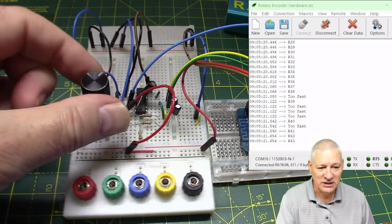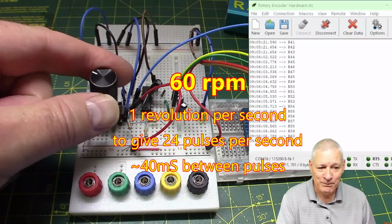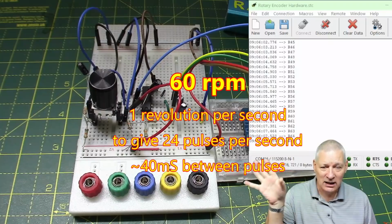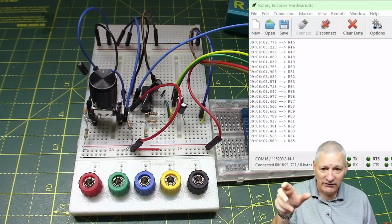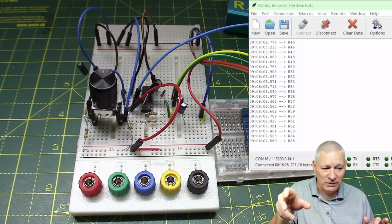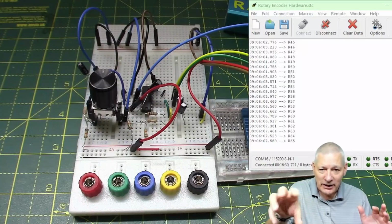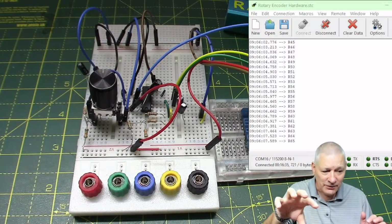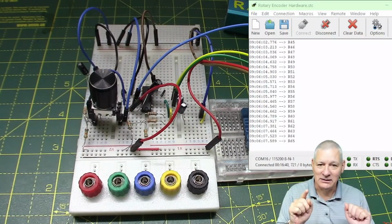You've got to turn this no faster than the equivalent of 60 RPM. Which explains, I think, in some ways, why the rotary encoder in my car, which is a volume control and a tuning knob as well, if I turn those too fast, nothing happens at all. I want to turn the volume up real quick, and I turn it, nothing happens. The volume does not change. If I do it reasonably slowly, then it goes up and back down again. But a fast turn does nothing. Exactly what I've now had to do on here. And I thought, why is this?